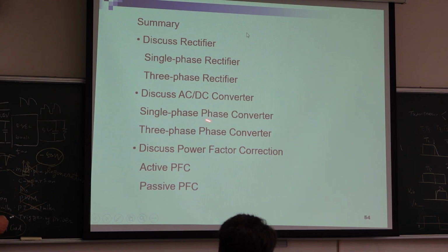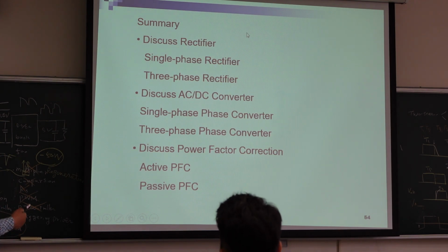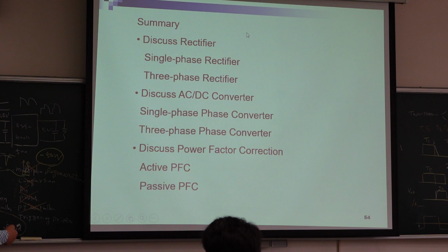So in this case, can you apply this idea to high power? The answer is no, because you have 20 amperes go up and then jump to 0. Then you create EMI. You interfere with every cell phone, every computer, every facility. So this can only be used for low power, but not high power. For high power, you still need to use two stages and use average current, not discontinuous current.